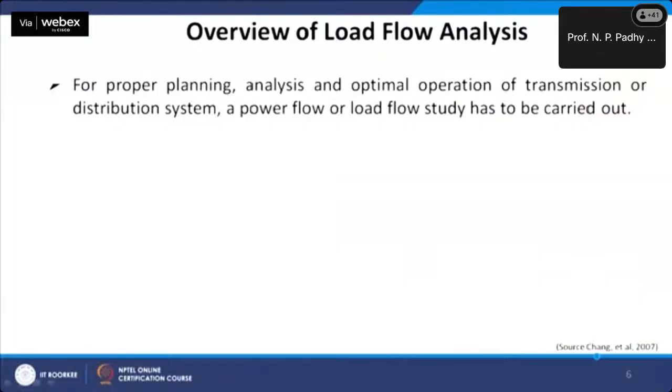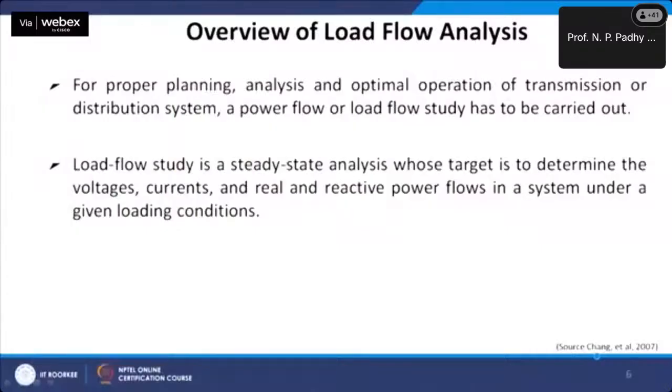Now very quickly, the overview of load flow analysis. For proper planning, analysis and optimal operation of a transmission or distribution system, a power flow or load flow analysis becomes a must. Now load flow study is a steady state analysis whose target is to determine the voltages, currents and real and reactive power flow in the system under a given loading condition. So if the loads are known to me, I must be in a position to determine the voltage at each and every bus, and the real power and reactive power flow in each and every line need to be determined.